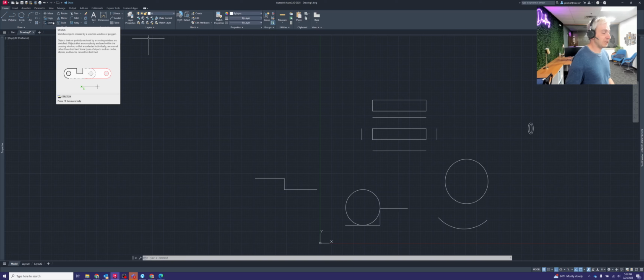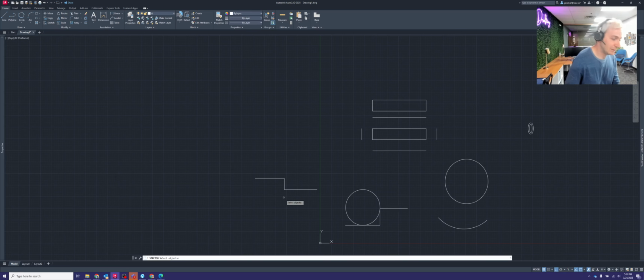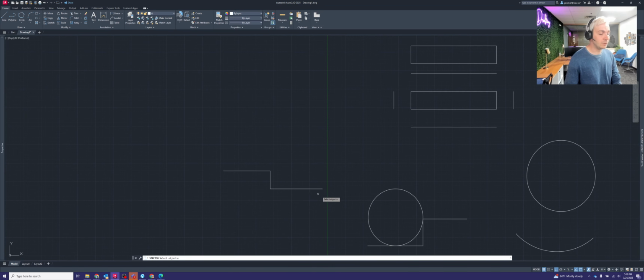When you start the stretch command by default, the first thing it does is tell you to select an object. Now, you don't want to go around clicking on parts. Like if I clicked on this, it's just not going to work. So it's confusing the way they worded it, but don't get too bogged down by that. In order to get around that, what you're going to do is start by thinking about it like this. If you wanted to extend this line out, let's say you want to make this 5 inches longer.